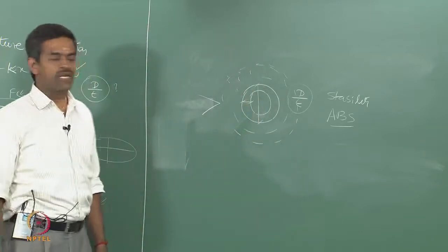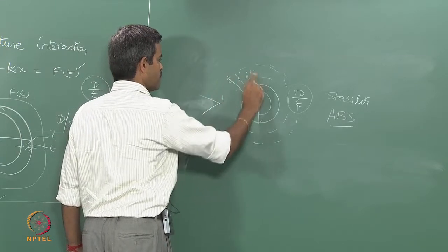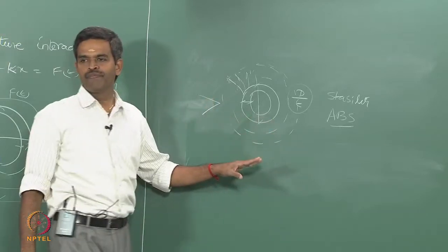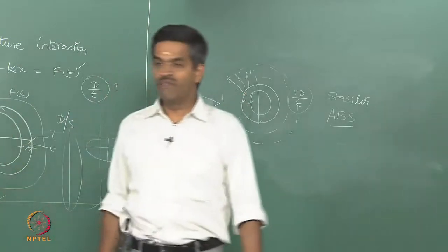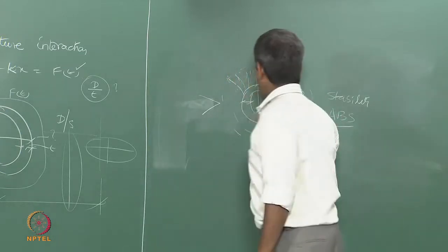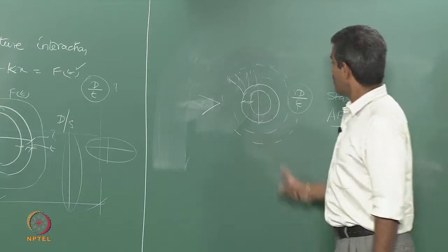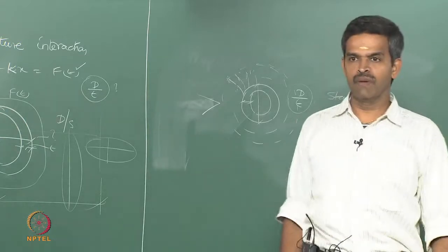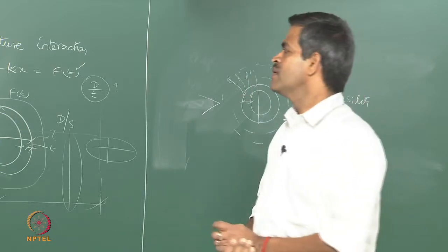Now, as you keep on seeing here, when they are getting radiated away from the source, they will start blocking the action of the force on the member. So, there is always radiation damping caused, that is what we say here, wave radiation damping. This can be of two forms. One, because of the high amplitude motion of the cylinder itself, if the cylinder is flexible, or because of the rigidity of the member which reflects the wave particles hitting the member. So, it can be two forms, therefore, there is one important source of damping.